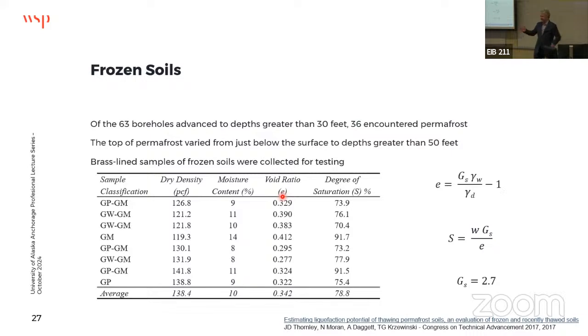But liquefaction happens on a spectrum of soils. And this is really focused on, say, a clean sand approach, but you can still see it in a variety of soils. This is the kind of liquefaction where you go to the beach, the waves come in, the waves go out, and you sit there at the high tide line and stomp the ground. Yeah, you can see the sand liquefy. It's exactly like floating.